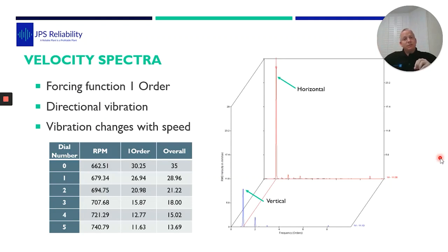If you stiffen up the strings, the pitch goes higher, so you can stiffen something to increase resonant frequency. Add mass to lower the resonant frequency, and also you can use damping to dampen the resonance. And the easiest one of all is change the force and function, but unfortunately with this one here, you can't change the force and function.